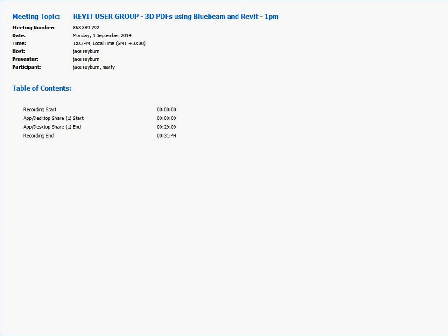You set up scope boxes. On those scope boxes, you can do a thing called a plan region, so you can independently control one of those areas and not muck up the other one. That's the perfect one to go through. In fact, there'll be some good movies on YouTube on that. I'll dig those out. So you can have independent views, and it doesn't affect the other one, is that correct? So the tool is plan region.